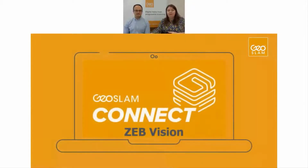So let's go into a ZEB Vision demo here. You'll notice that we've got 3 key steps after processing the initial SLAM data. We have a stitcher, which stitches those 2 lenses together, a position creator, which creates your trajectory and your image walkthrough, your bubble view, and then we've obviously got colorization, which is your final step.